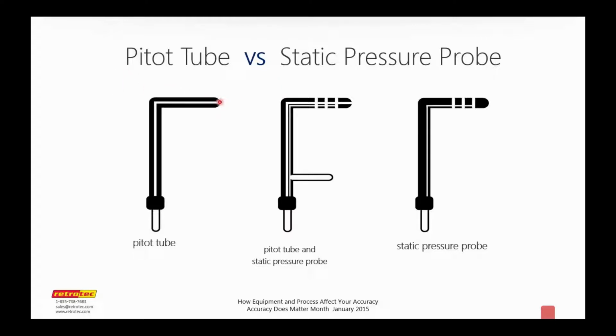We can cause all kinds of turbulence, or actually wind pressures moving inside it that are not giving us accurate readings. This one's a little bit better, but we can still get air moving in front. But now with the actual static pressure tube, we do not have to worry about which way this thing is pointing, and air actually blowing directly into the tube and giving us skewed pressure.